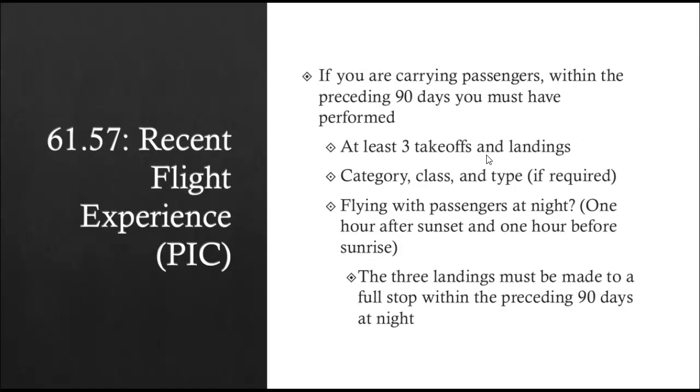Federal Aviation Regulations Part 61.57 lists all of the recent flight experience requirements to operate as pilot in command. Once you get your private pilot's license, it never expires, but you do need to stay current by meeting certain requirements listed in FAR Part 61.57. If you are carrying passengers, within the last 90 days, you must have performed at least 3 takeoffs and landings in the category, class, and type of aircraft if a type rating is required.